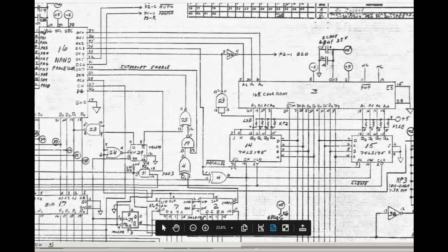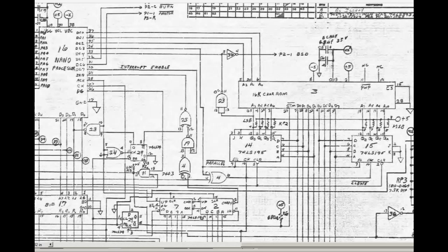So if it wants to load data into the shift registers, it lowers this line, and that puts the shift register into a mode where really the shift register itself is disabled, and this just then acts as 4 D-type flip-flops. They're daisy chained, so it acts then like an 8-bit D-type flip-flop. And then whenever a clock pulse is applied, whatever data is on the inputs makes its way through and is latched to the outputs. It does that on the rising edge of the clock.